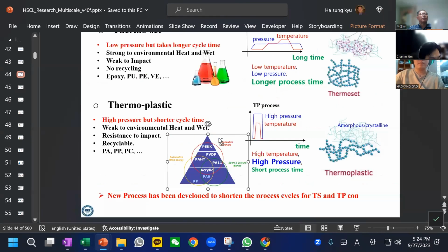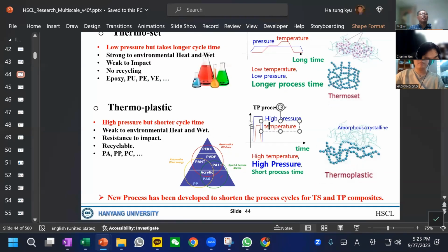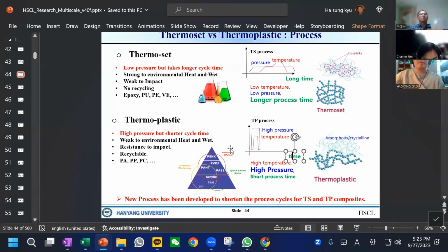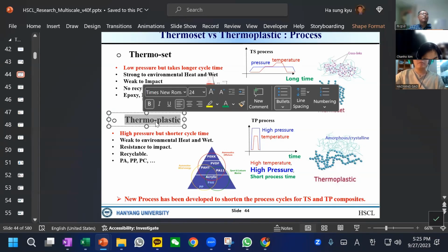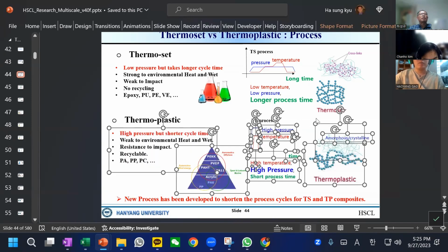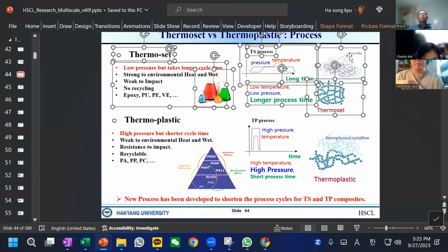Why thermoplastic has become very important compared to thermoset is that we can make thermoplastic composites very easily. How? You just apply high pressure and temperature, the time is very short, done. Also, reversely, when we apply heat, it can become plastic again, so we can redeform and recycle. That's the characteristic of a thermoplastic. But with a thermoset, it's chemical bonding; the cross-linking cannot be dissolved or broken.